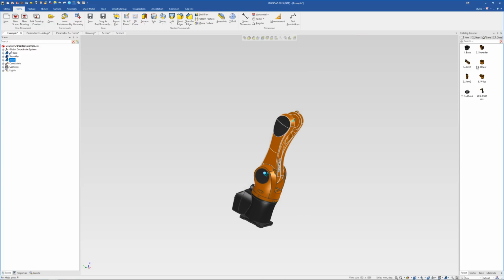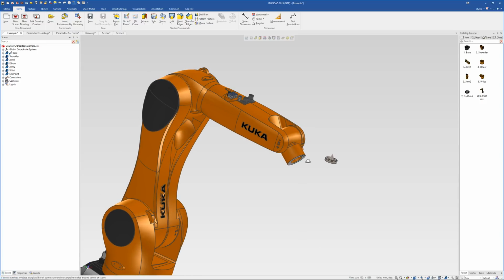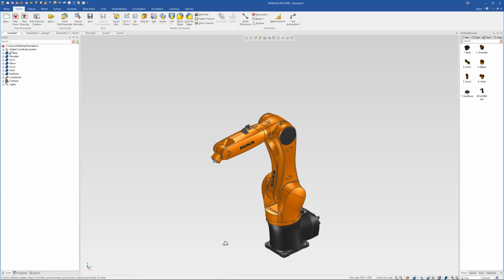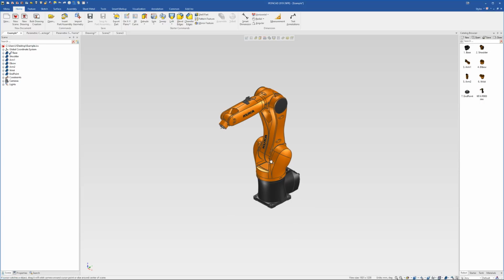And we've got the elbow, arm, and wrist and the endpoint. Oops, missed the snap point there with the endpoint. As you can see, don't want it over there. Just want to make sure we get onto this so that it snaps into place. So with this model, it's got some nice smart attachment points sitting on it so that it will automatically give you some movement constraints there.